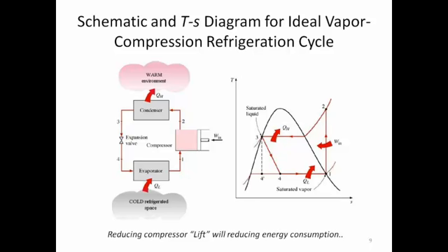They all work the same. Where the energy required to pump the heat comes from is this work right here between 1 and 2. It is pressure that you're increasing. You increase pressure, it increases temperature due to ideal gas law. And it's this work that's going in.